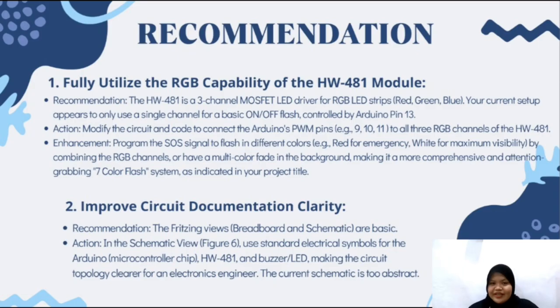Last but not least, first, I recommend to fully utilize the RGB capability of the HW481 module. The HW481 is a 3-channel MOSFET LED driver for the RGB LED strip, which is red, green, and blue. The current setup appears to only use a single channel for a basic on-off flash controlled by Arduino pin 13. For the action, we can modify the circuit and code to connect Arduino pins 9, 10, and 11 to all 3 RGB channels of the HW481.